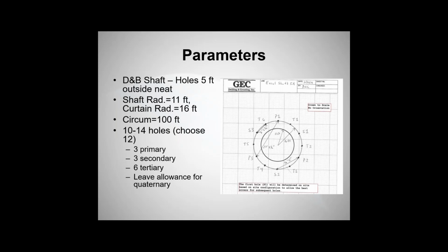Again, a lot of people have this picture in their mind. They think this is because you don't want the rock bolts to punch through, or you don't want all this. That's not the case. Go back to the rock grouting webinar. Cementitious grout travels a tremendous distance when it's pumped under the right circumstances. Limiting the distance is our problem, not how far we can get it. This is simply because we want to minimize the grout that we're excavating.